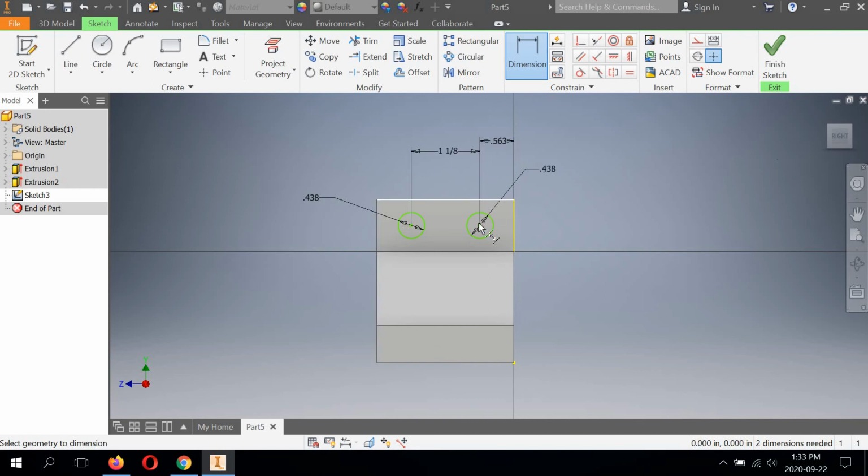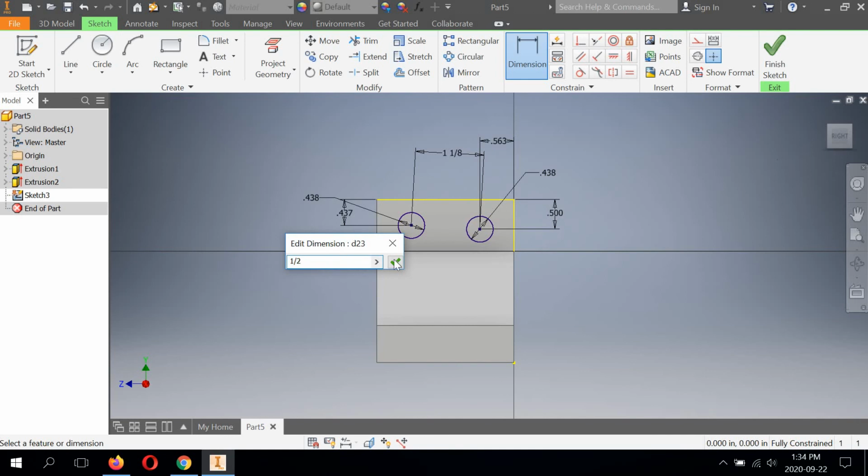And then one last dimension from here to here, from the top surface to the center point of the hole, is listed on the top. It's different. It's 1/2 inch. So 1/2. Same thing here, 1/2. Okay, and we're constrained. That dimension went crooked for a bit, and after I inputted the 1/2 inch here, it straightened it out again horizontal. So that's how that should look.